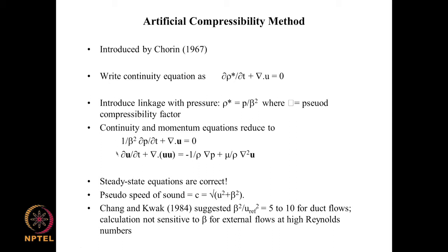So by rewriting the equations in this way through the addition of this artificial compressibility term, we are creating a method of finding P and putting that in the momentum equations, so that when we get to the momentum equations, it is no longer a nuisance variable, it is a known variable, and it varies from point to point because it is given by this equation here. So this makes pressure a function of x, y, z, t, and that variation is obtained from this equation. So that same variation is put here to get u.